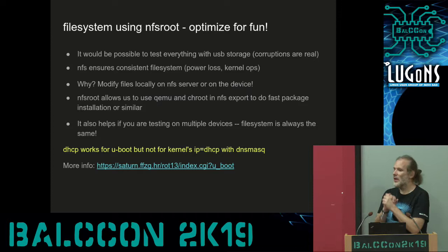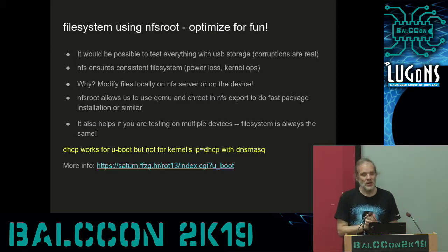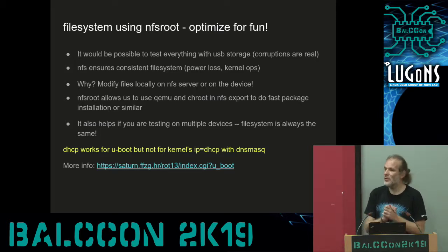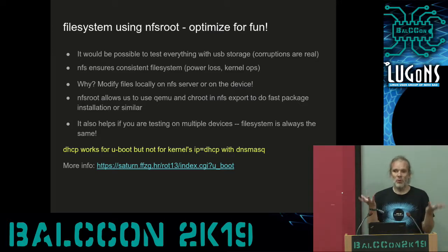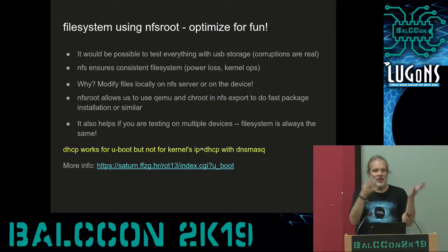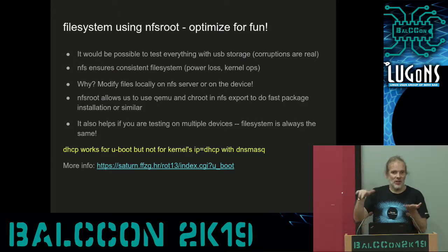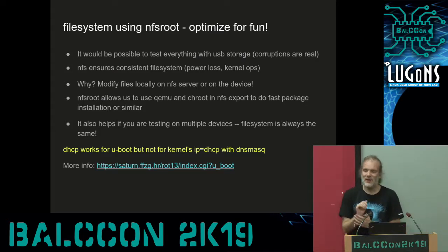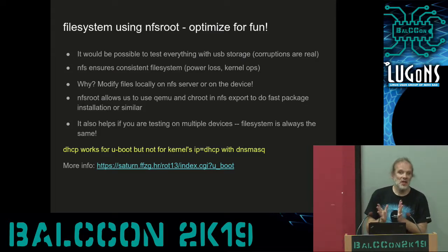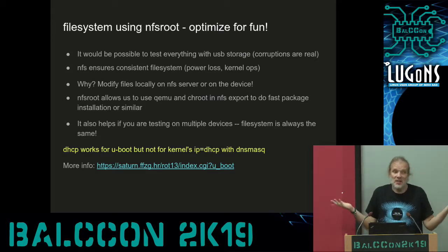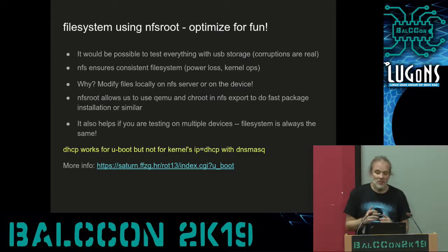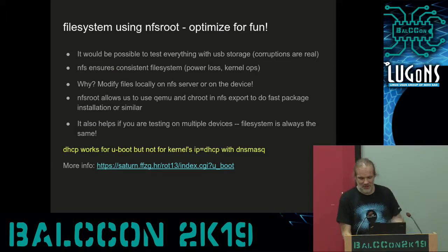In this process, I learned a valuable lesson. If you are developing something for an ARM board and you will compile the kernel multiple times, my suggestion is to actually set up NFS root. It will save you so much time, especially if you have multiple boards. For example, I used one board while the other was charging, and it was super simple to exchange it because all the data were on the NFS server itself. Also, a word of warning: for me, U-boot would happily take the IP address and DNS mask over DHCP, but the kernel wouldn't. So the command line option ip=dhcp, which should work in the kernel, actually doesn't, but you can hard code the IP, and that's okay.